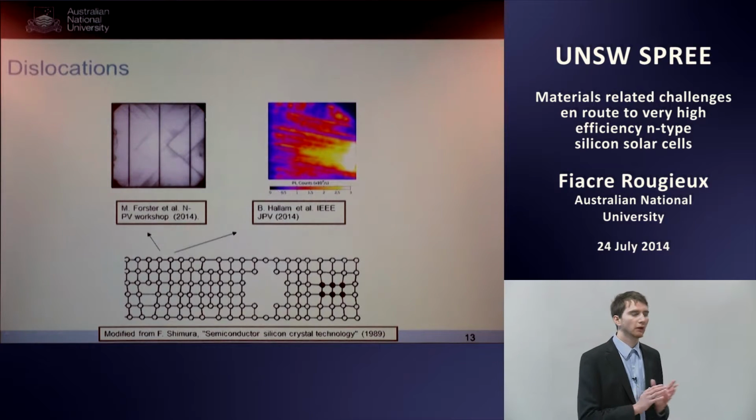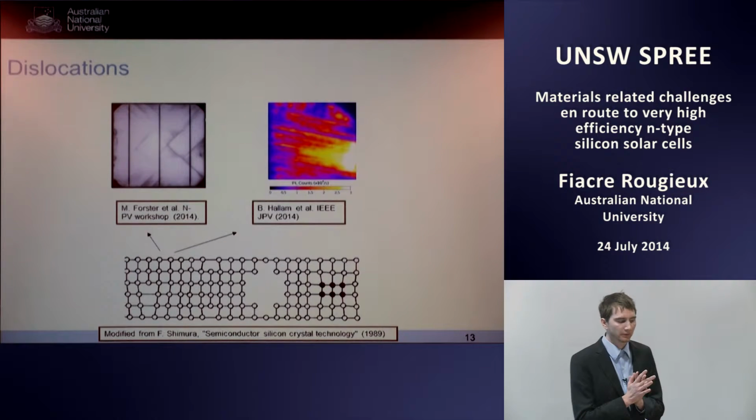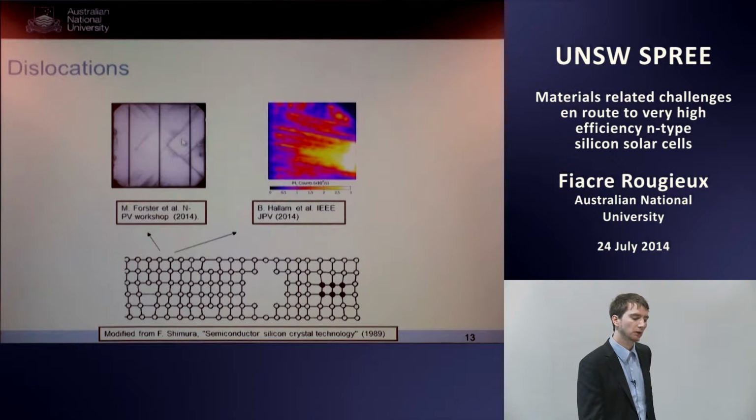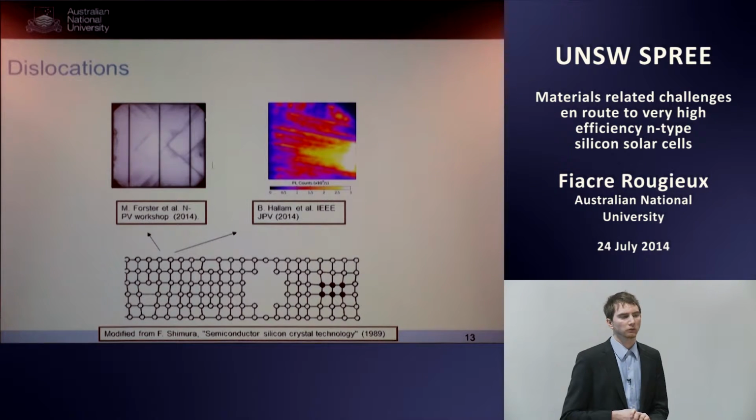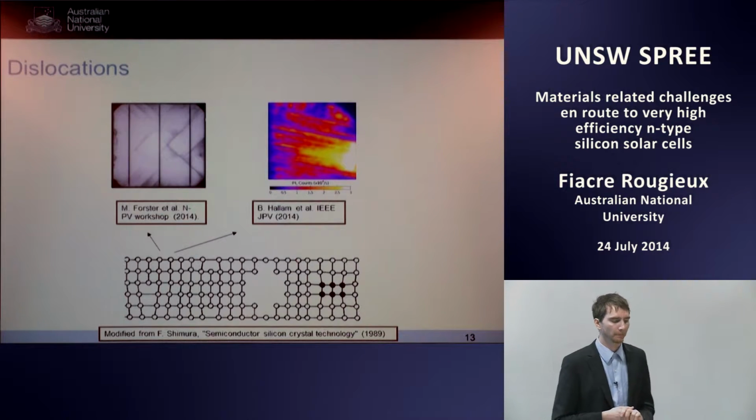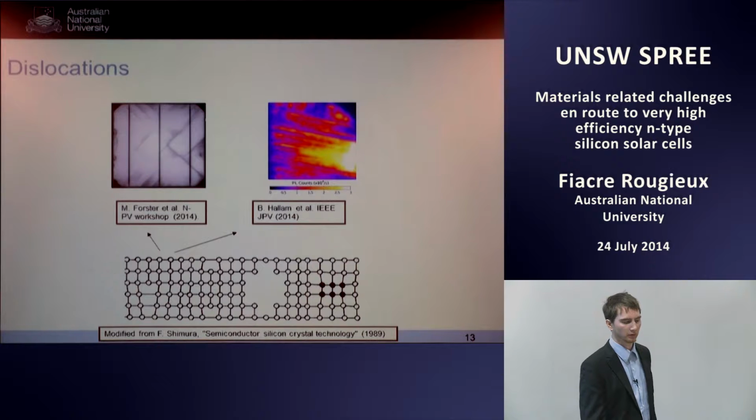The worst scenario for us, and it does happen sometimes, is if we have dislocations, and we have dislocated monocrystalline ingots from time to time, and you can see here in this PL imaging again those slip lines here or here. It can also be created due to too great an amount of impurities, which is the case here.